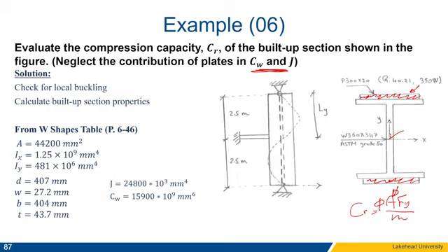In that example as well, there is an elevation view of the column. So the column is pinned obviously like that, and the column is supported in the middle. But keep in mind, based on our discussion, that will limit the buckling length only in one direction.